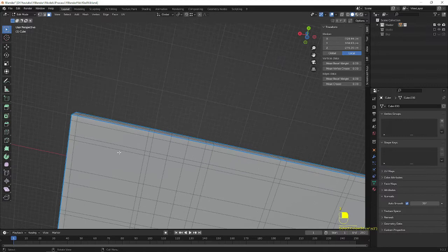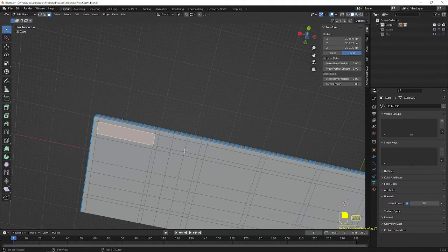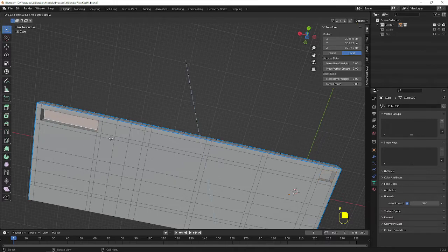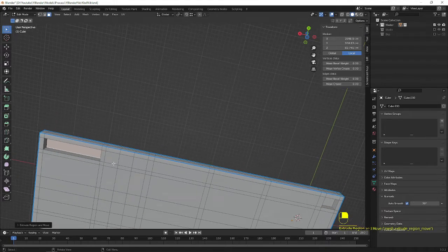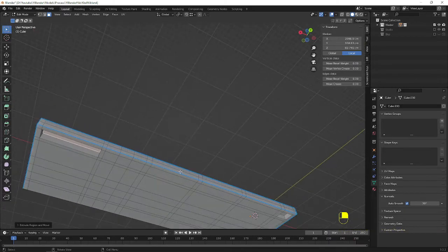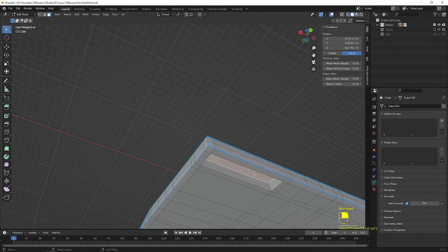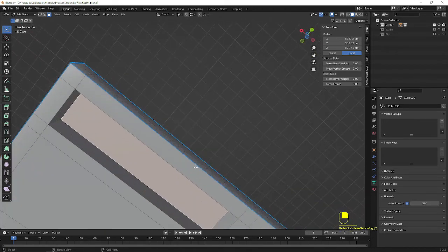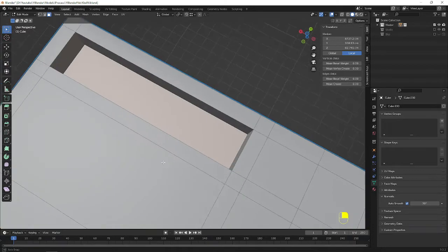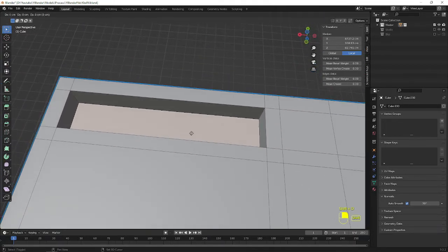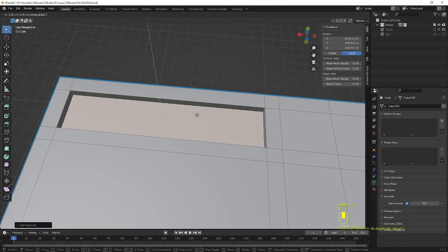I'm going to select here one and select here one. So using the same shape I'm going to give the design for this. E to extrude in Z axis. Okay, now each thing I'm going to do it. Shift D and right click to cancel and GZ.